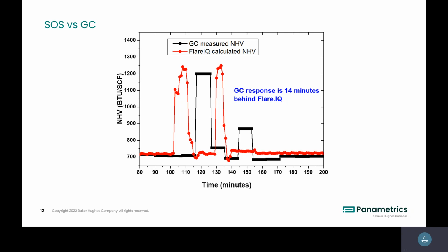Of course, if nitrogen changes 5% during that upset condition, you have 5% or 3% error in the steam calculation or heating value calculation. So what? An extra 3% error, but you're still doing most of the work, which is preventing black smoke. Instead of setting the heating value at 270, you set a 10% buffer, and then it's all covered.